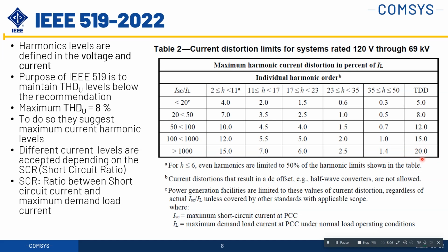Correct. So we can see here 20% THDI, or say 20% TDD, is absolutely allowed in the IEEE 519. So we don't have to reach 5% all the time. Yeah, so in theory, misinterpreting this can give you an 80% higher dimensioning of the products to mitigate the distortion. Quite a lot of money to save here, and room area, sizing area.